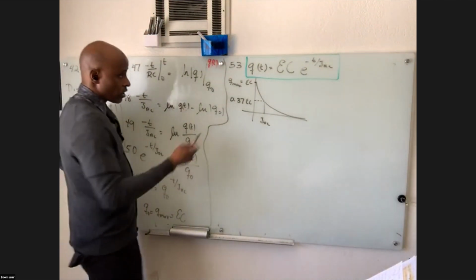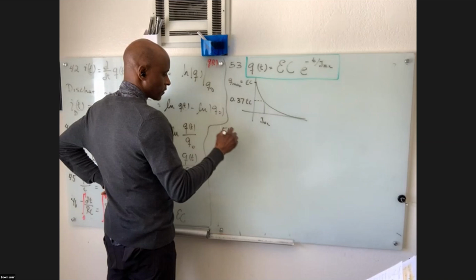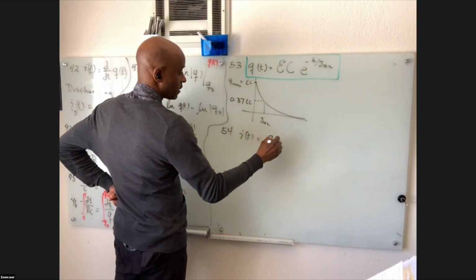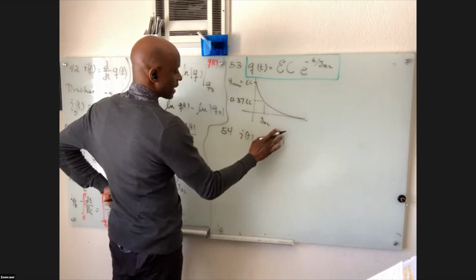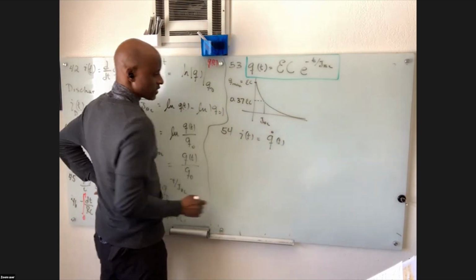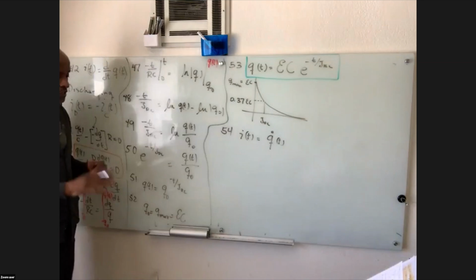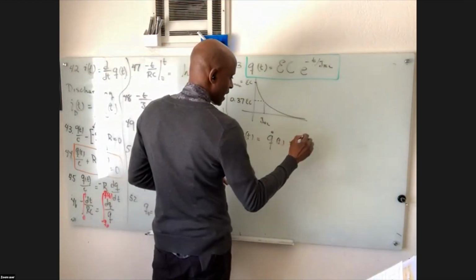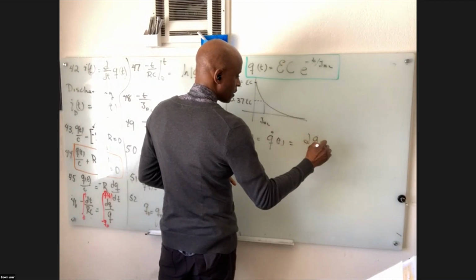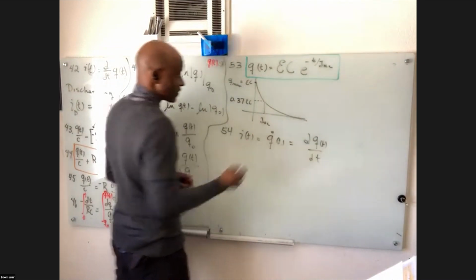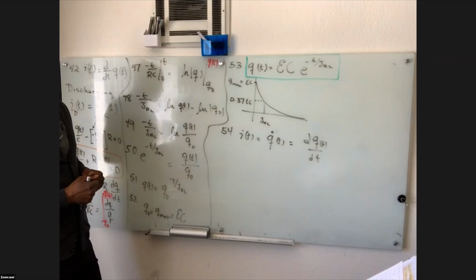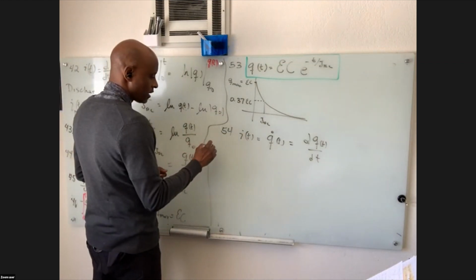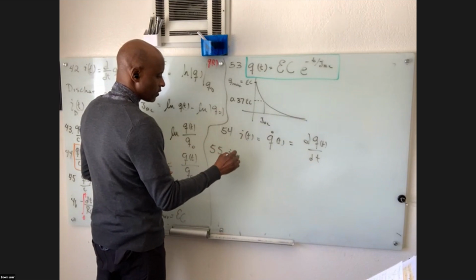the functional form of the current, we just take the derivative again. So I of t is just going to be equal to Q prime, or Q dot, excuse me. Remember using the dot notation. Dot notation is equivalent to prime notation. Q dot means derivative with respect to time. So dq of t dt. And if we take the derivative of that, we get the same thing we got before, that I of t is going to be equal to,